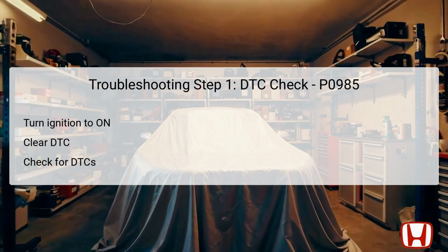The first step in troubleshooting DTC P0985 involves initiating a detailed DTC check using the Honda Diagnostic System, HDS. Begin by turning the ignition switch to the on position without starting the engine. This enables the onboard systems for diagnostic purposes. Next, clear any existing DTCs from the system using the HDS to reset the fault codes.